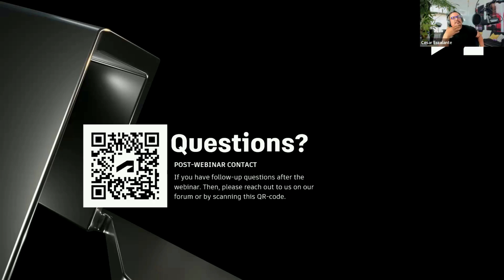And if you work with meshes, you know that meshes are a little ugly when it comes to manipulating original primitives. The conversion of a mesh into NURBS, more often than not, works, but sometimes it generates additional triangulations that were not computed in the original Forma primitive, and that triangulation hinders the proper representation of the mesh as proper Rhino objects.